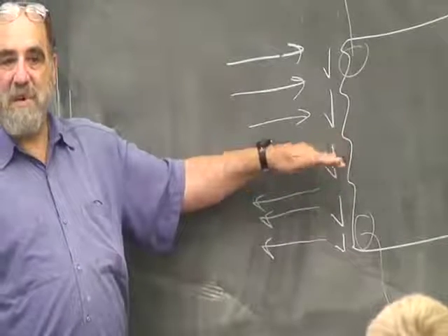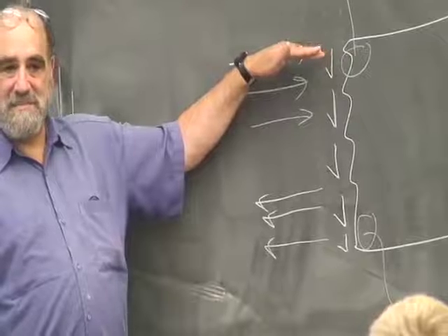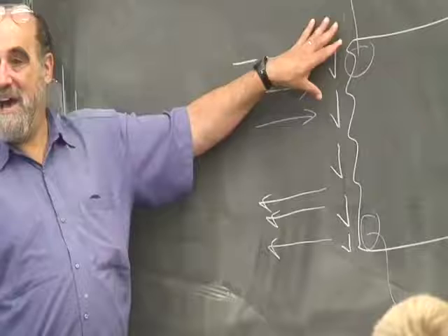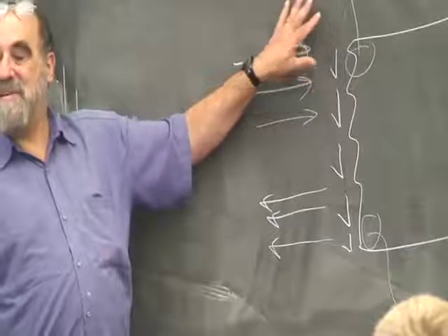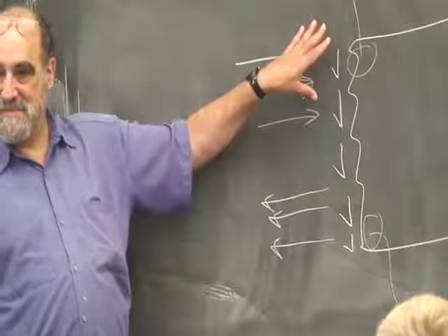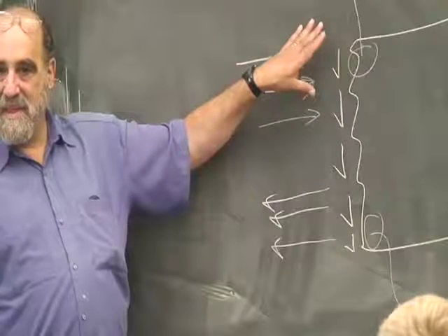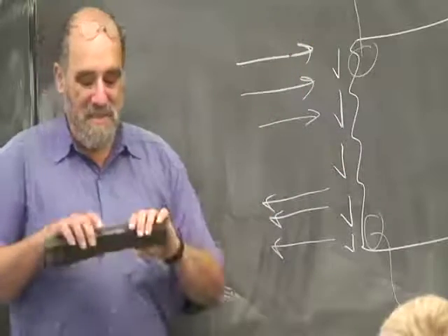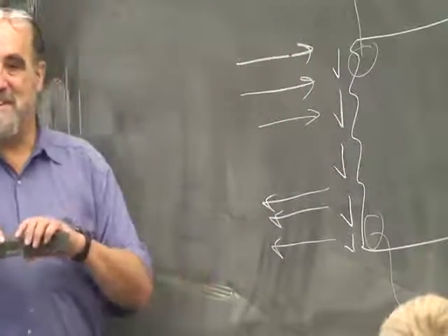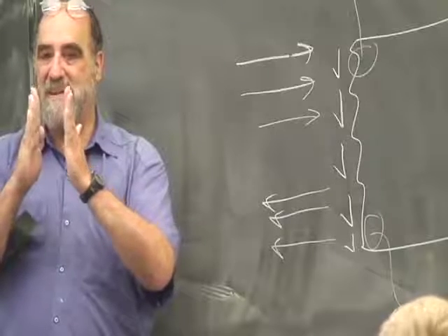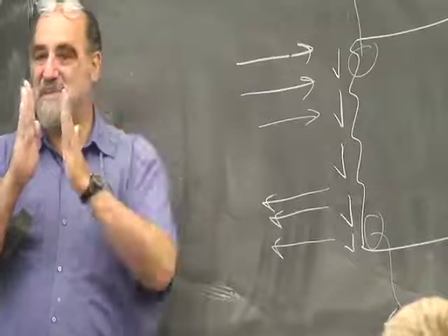So that means we get a proportionality of H. But the bigger H is, the more fibers we have. So that means we have a proportionality factor of H squared. But the bigger H is, the more each fiber is stretched. Because when this squeezes like this, the middle ones don't stretch much, and the top ones stretch and shrink a lot.